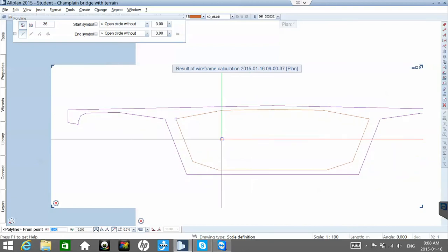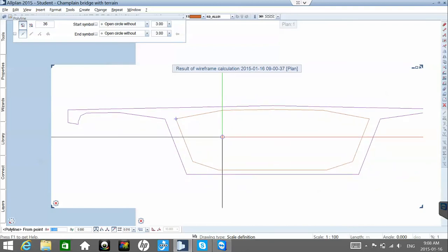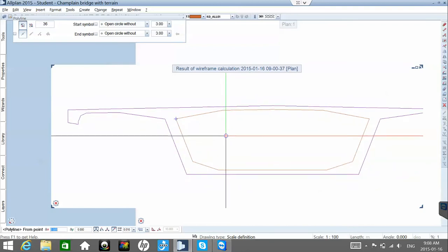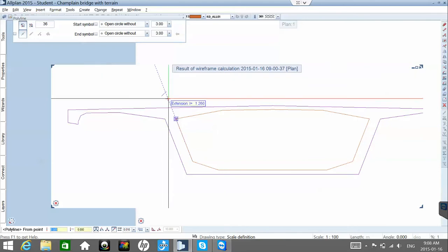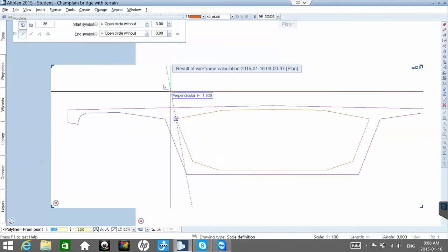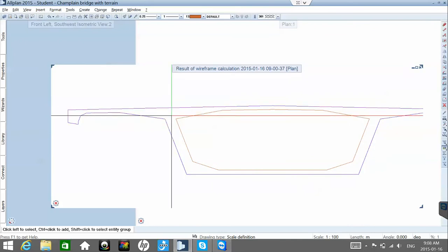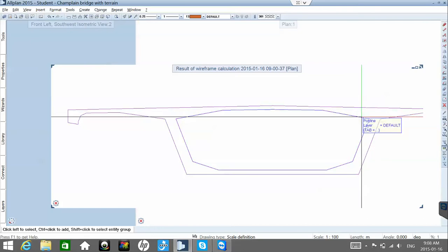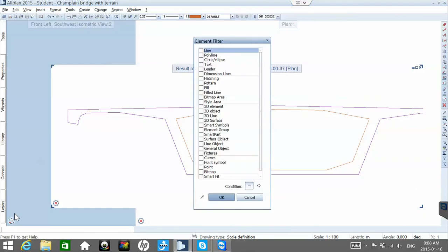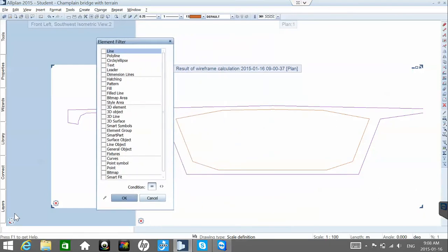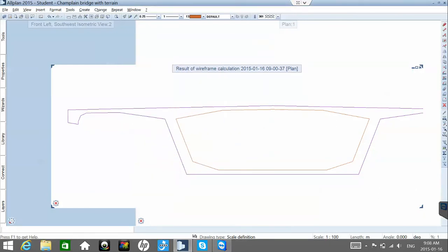Okay, so now you should pick this brown outline you just drew and copy it by a known corner. So escape. Try to select the brown line. If you are unable, you need to use a filter for the line, because you already have a polyline beneath. So you should use a filter based on colors. So you filter only color 13. So not that one, you should hit cancel.